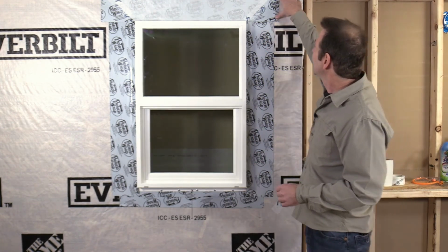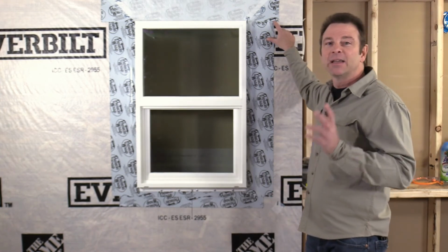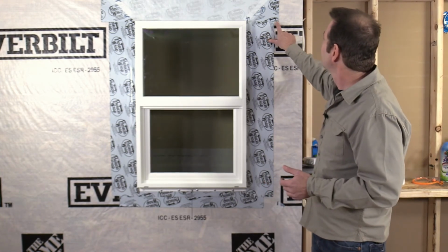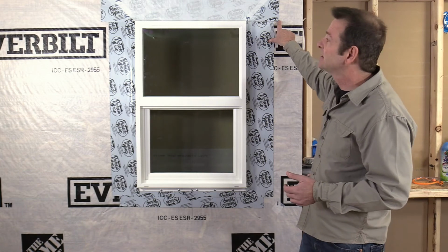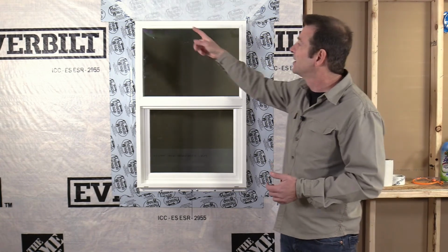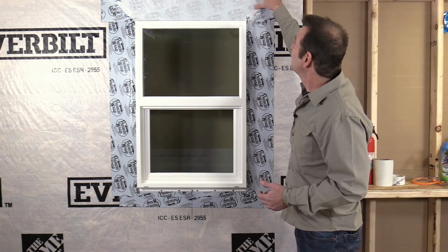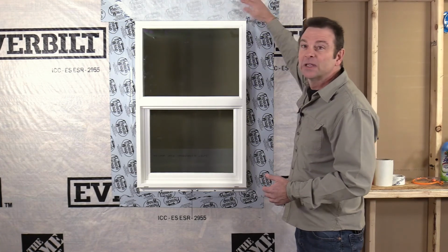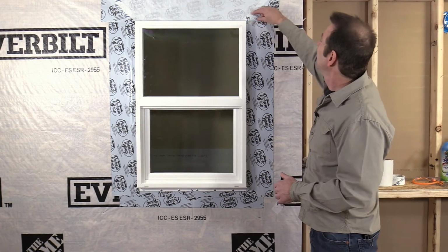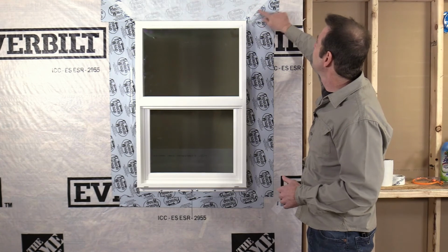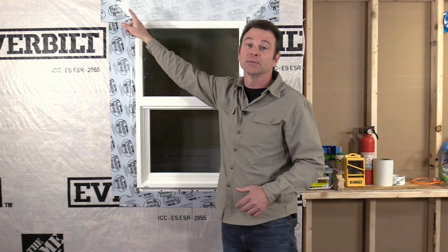Same for our top flashing, and most information will tell you to overlap your head flashing an inch more or further on the left and the right. That's a pretty typical spec. When it comes down to the final step, there is a house wrap flap here that's folded down over this whole assembly, and you will have a sealing tape on each one of these angled pieces.